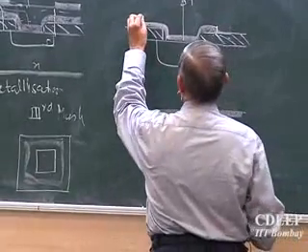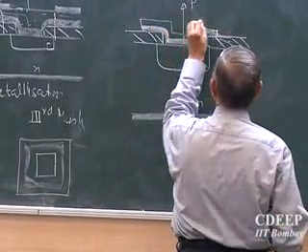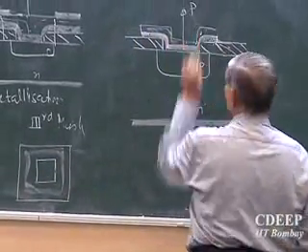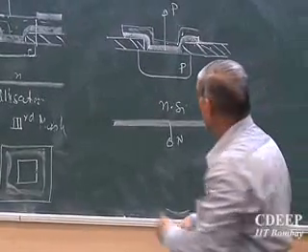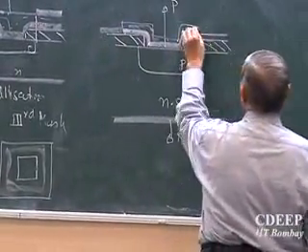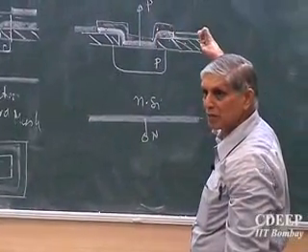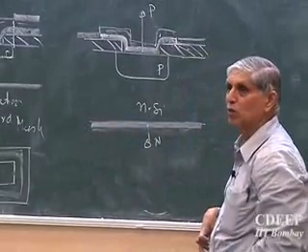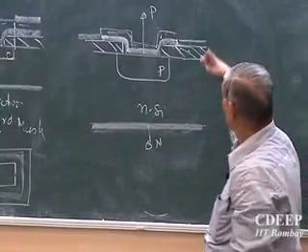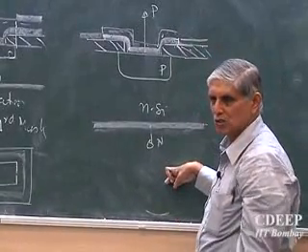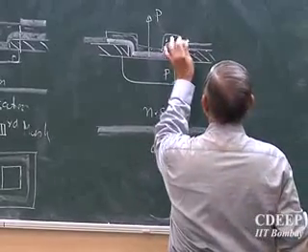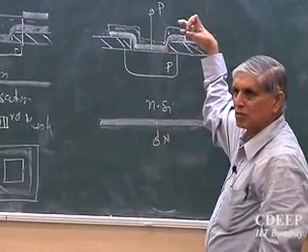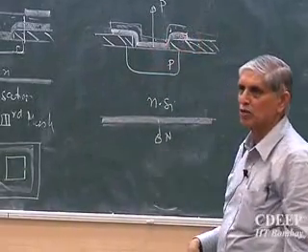Okay, since this portion has the resist, because the window I opened is clear, this portion of resist becomes hard. Is that correct? The rest of the aluminium does not have resist because that was developed away. So when I dip this, and of course I also coat the backside with a resist because I don't want to etch the backside metal, or even you finish this and then coat, that is also possible. And then you etch the aluminium, so this aluminium will go. Then strip the photoresist, so you have the contact left only in a small area.